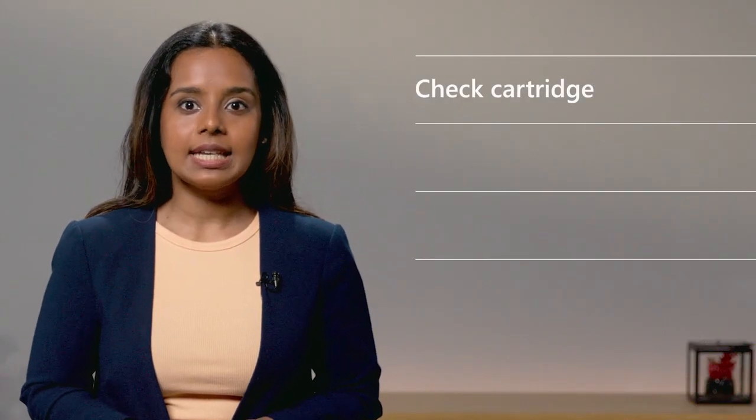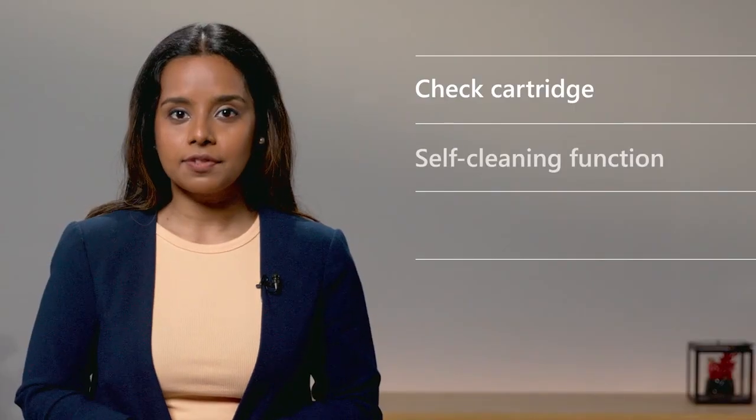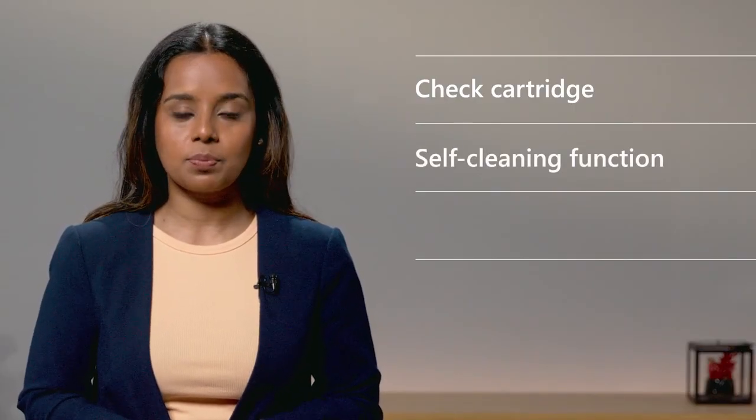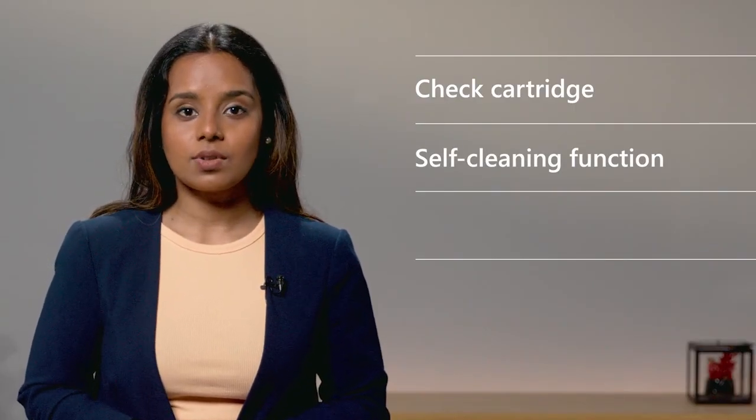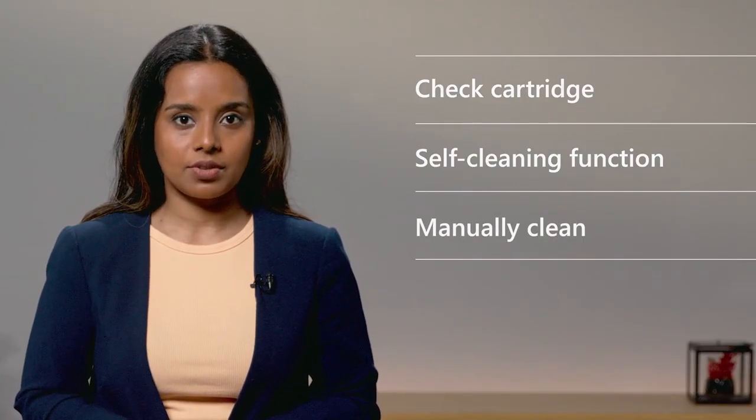Third, poor print quality can manifest as faded prints, streaks, or smudges. This issue often stems from either low ink levels or clogged print heads. Start by checking and replacing any low ink cartridges. For clogged print heads, most printers have a self-cleaning function that can be activated through the printer's menu. If this doesn't resolve the issue, manually cleaning the print heads with a damp cloth may be necessary.